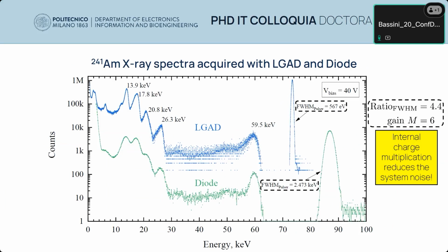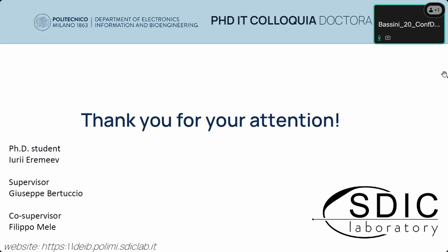And this is not the only message of this work, because to study the noise of the structure, we analyze the dark current parameters. Dark current is the DC component of thermal generation in the structure, and noise parallel spectral density is the AC component. Together we can find the optimal parameters to use this structure in spectroscopy without even a radiation source. Thank you for your attention.